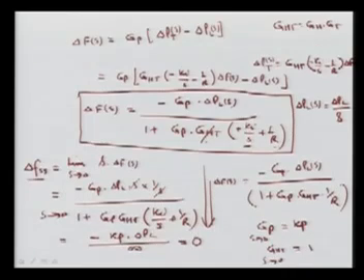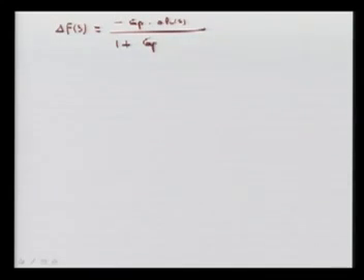And then we have to solve. So this simplified will be, again I can write the change in frequency in the Laplace domain, it will be nothing but minus Gp, change in PL(S) divided by 1 plus Gp, and again here Ki over S plus 1 by R, and for this we have to derive the response. Here again we want to see the step response, so the PL(S) is nothing but the magnitude PL divided by S. So we can put that value and we can see what we are getting.